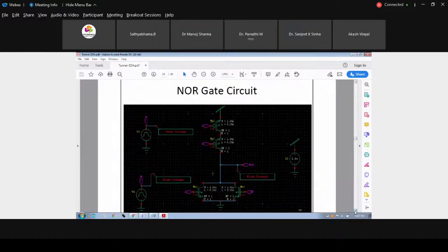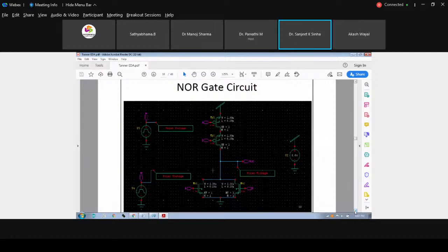Okay, this one is the typical NOR gate implementation, where the two PMOS come in series and the two NMOS come in parallel. Since we are having two inputs, you can use, as we discussed when selecting the instance for the voltage sources from elements, the different pulses here. So here it is, you can say a fixed pulse. Yes, next. Now we'll see the waveform.